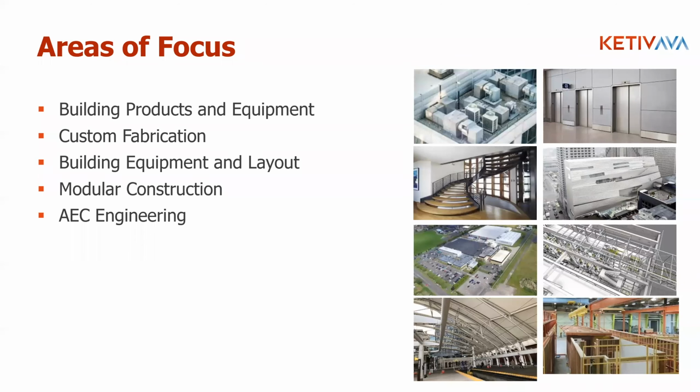You would have got a lot of performance hits because it's trying to load in that full Revit file, the full project. Whereas now you can really tailor the area where you're going to be focusing in terms of your design inside of Revit, so that when you bring it into your model, you're not using all your processes and all resources within your computer system to run the project itself. So we'll dive into that shortly, but there's a particular workflow to minimize what you're actually bringing in from Revit inside of Inventor.